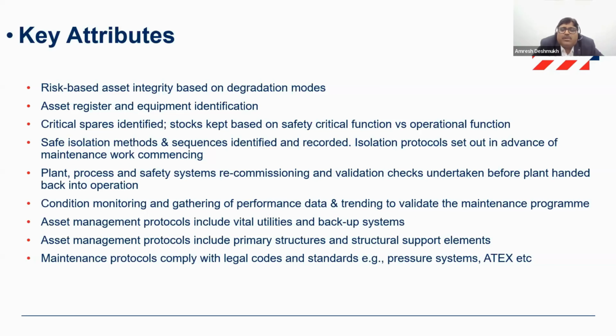Ensure that you follow all the legal compliances which are in place. Generally this has been adopted by most of the units and you are in legal compliance, but ensure that it doesn't become a tick box exercise. If something involves monitoring of your pressure equipment or measuring temperatures for hazardous materials that you're handling, ensure you are not doing it just as a tick box exercise, and that it's been taken care of well, at least for the safety critical assets that you have.